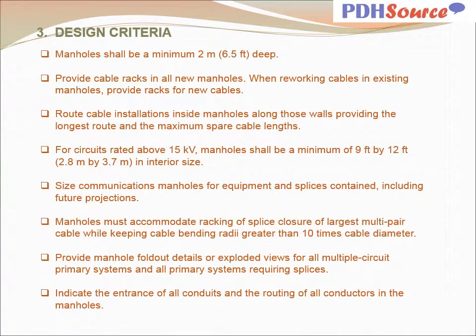Manholes shall be a minimum of 6.5 feet deep. Provide cable racks in all new manholes. When reworking cables in existing manholes, provide racks for new cables. Route cable installations inside manholes along those walls providing the longest route and the maximum spare cable lengths. For circuits rated above 15 kV, manholes shall be a minimum of 9 feet by 12 feet in interior size. Size communications manholes for equipment and splices contained, including future projections.